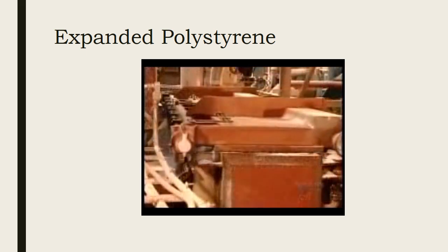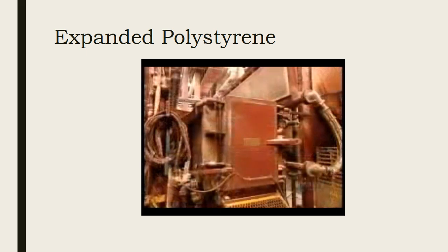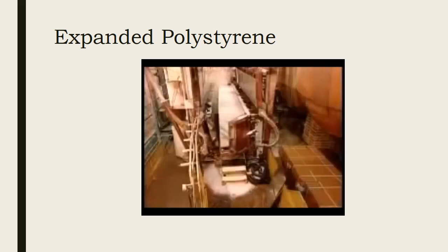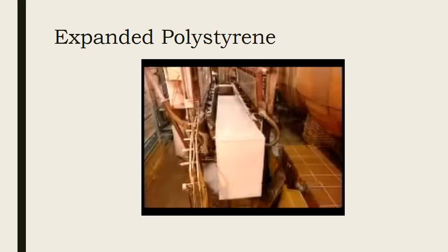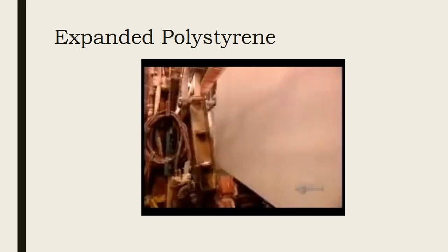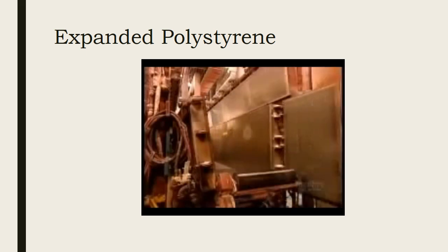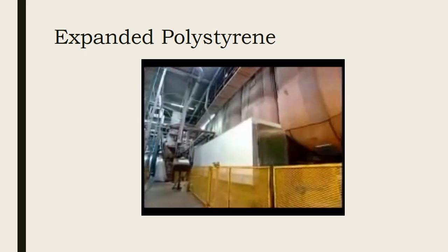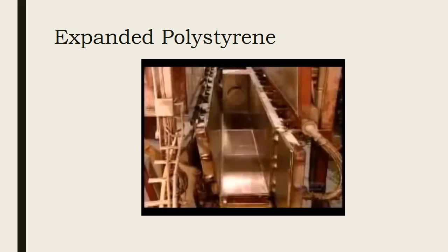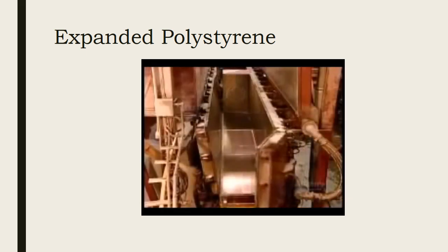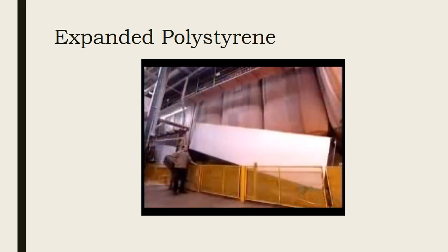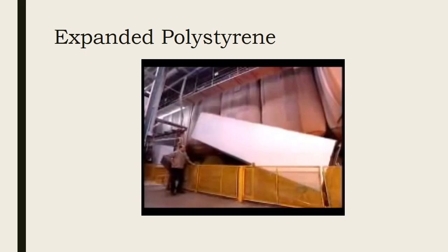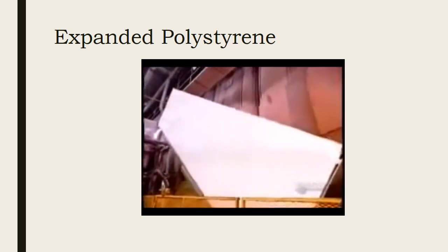They steam fuse the pellets together, molding them into a block that's roughly 5 meters long by 1 meter wide by 3/4 meter high. This molding process takes from 5 to 20 minutes, depending on the density. A scale built into the conveyor belt weighs the block to make sure it meets specifications. Depending on its density, a block this size can weigh anywhere from 45 to 200 kilograms.